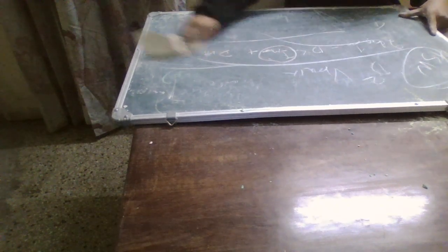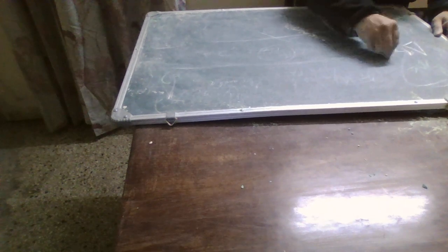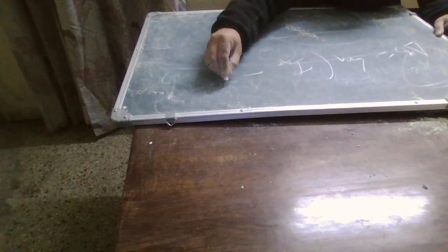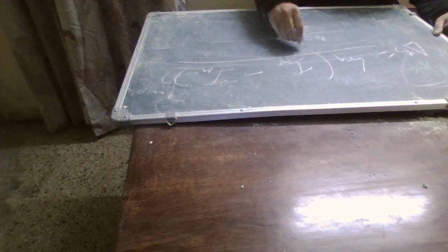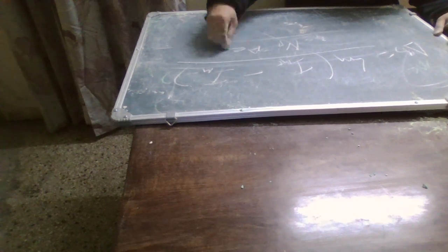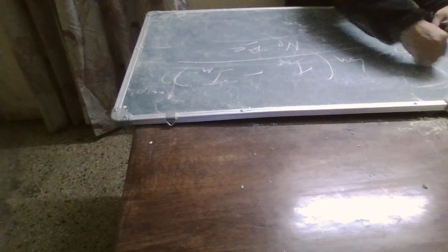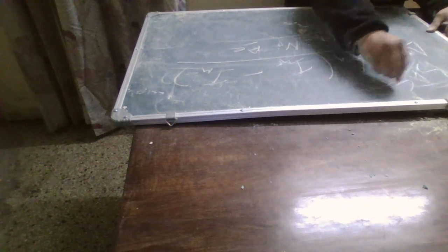Now we are going to get an AC flux density. How we are going to get an AC flux density? AC flux density BAC, let's take delta B equal to Lm of these magnetizing plus the negative magnetizing current divided by NP into the cross sectional area of the core. So this is how an AC flux density is calculated.